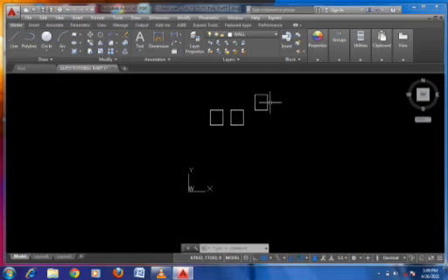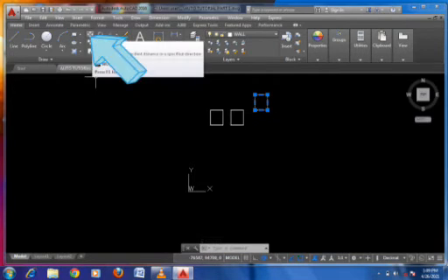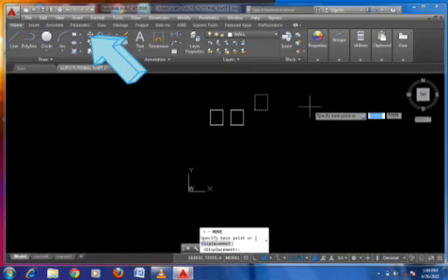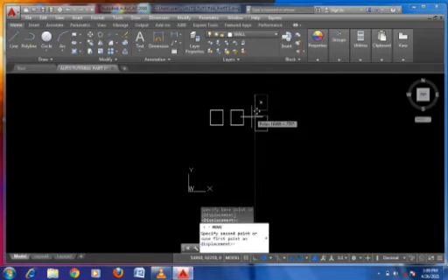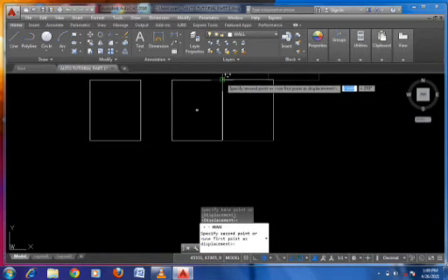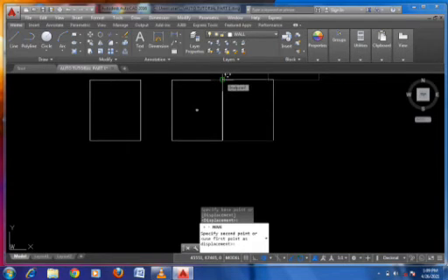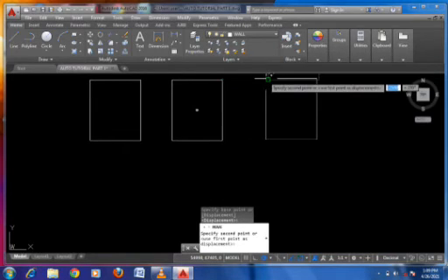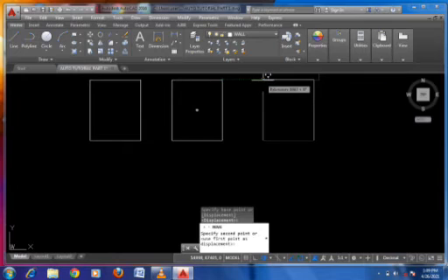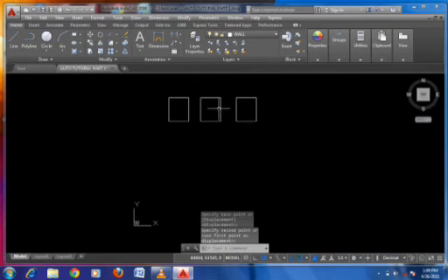Just click on it because they are in one entity. It is a continuous line. Press your move tool here. This is your move tool. Just click on it. Just move it to this point so they'll be in the same line. You won't press anything. You won't left click. Just take it to this point for you to snap, for you to track it, so that they'll be in the same line. Just press it down. So that is that for that.